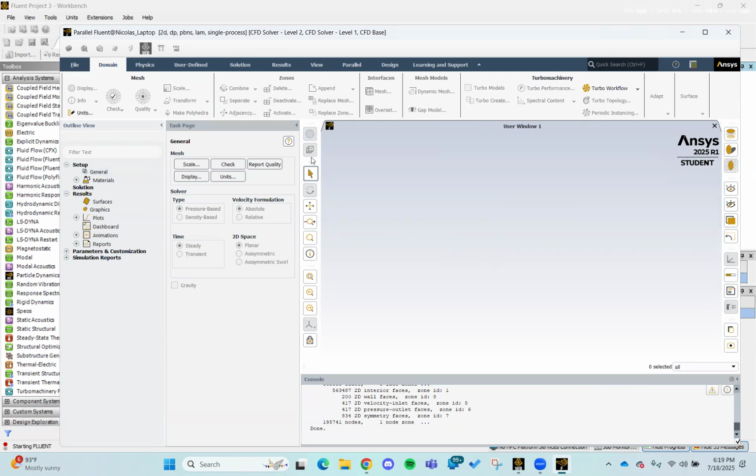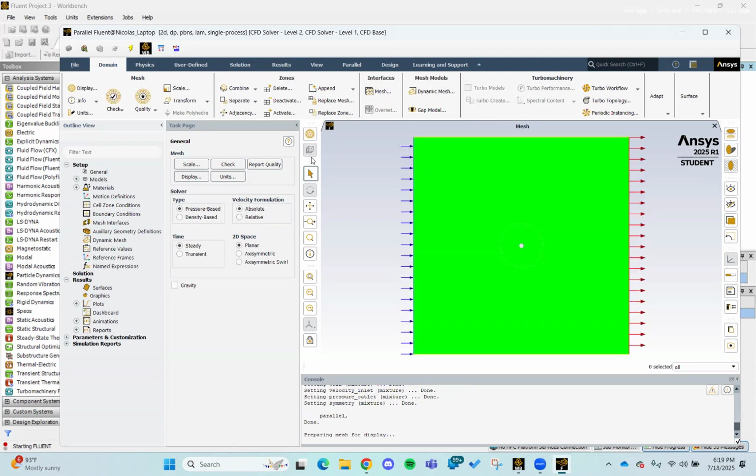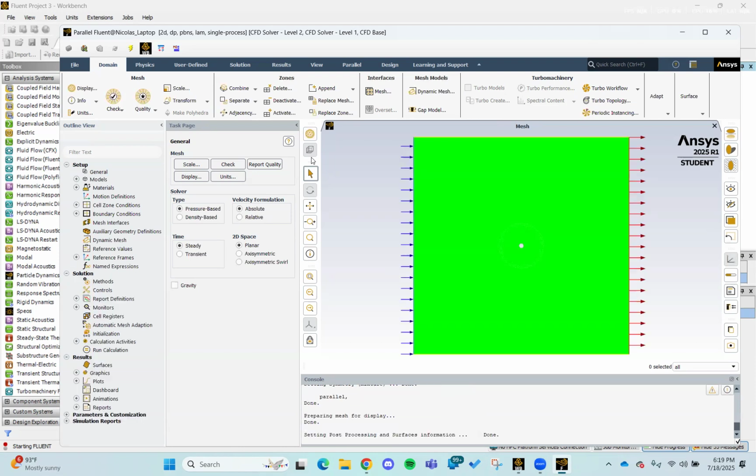While it's loading, I'll talk about why I chose things in certain values. I wanted to make my Reynolds number, our critical Reynolds number is 500,000. I decided to choose 55 as my Reynolds number to have a decent pace, nothing too slow, but nothing too quick, to make sure it's perfect laminar flow. Too slow wouldn't have really worked at first try, and it didn't work. But I'll jump right into what I've done.